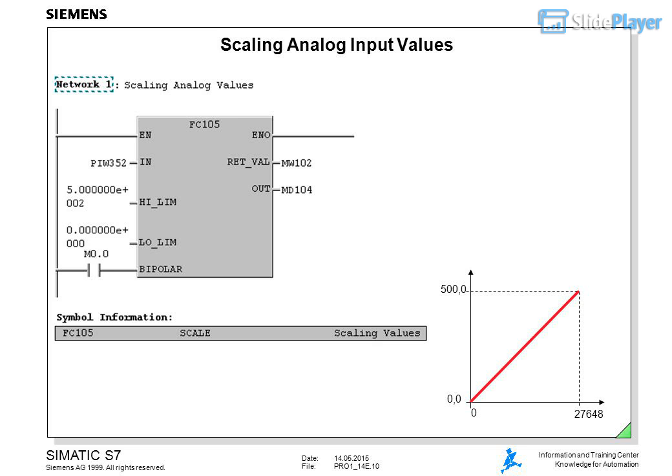Program standard block FC105 is used for scaling analog values. FC105 is supplied with the Step 7 software in the standard library, in the S7 program TS7 converting blocks. The analog value at input IN can be read in from the module directly or read from a data interface in integer format.